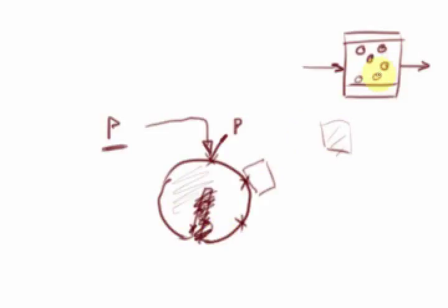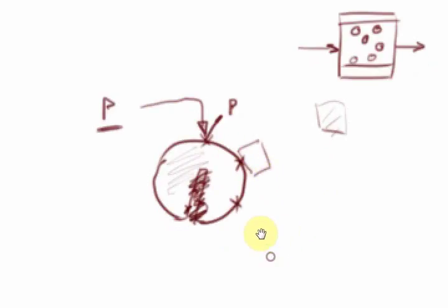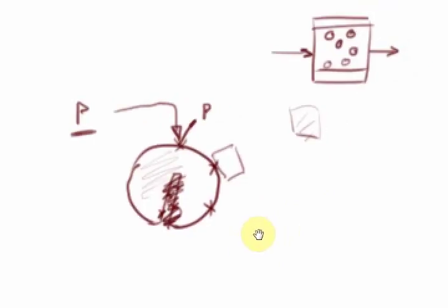So if you know that, let's say it's a fluidized bed and particles are smashing around, then you would look at using better materials for your support structure, so that there's a reduced likelihood of the loss of pores and hence the loss of catalytic centers. So there are various things you can do once you know what's causing the loss of activity. So that's one kind of macro thing that you could do.